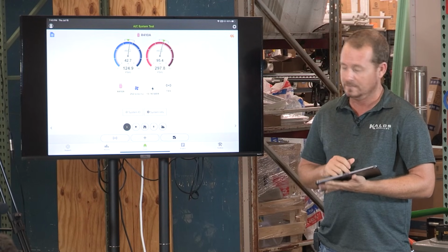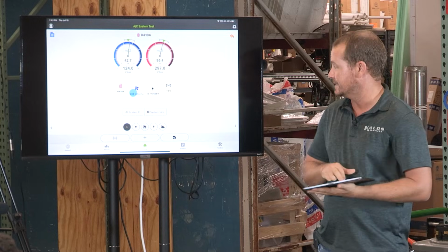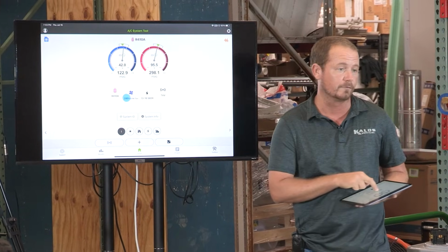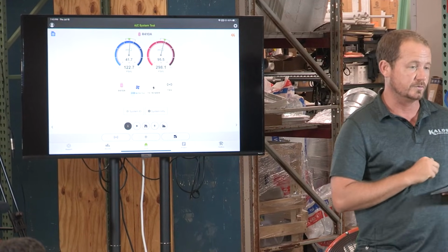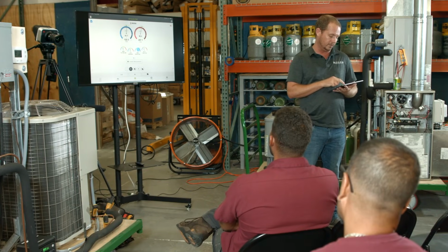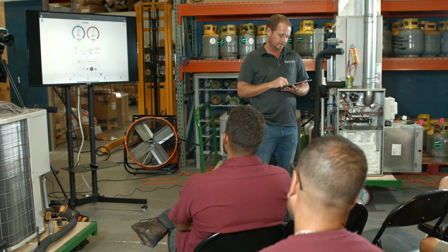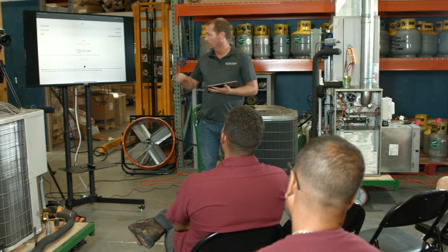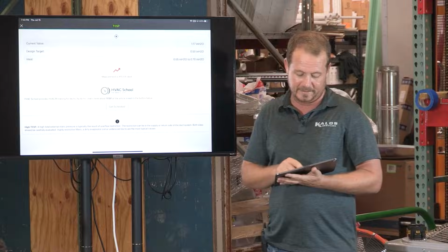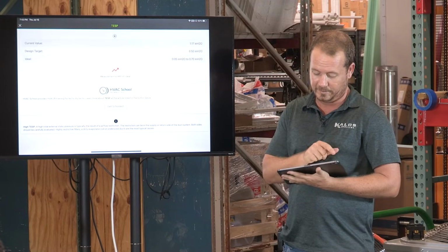Also, Measure Quick knows it's a problem because it's showing we're currently running 249 CFM per ton, which is way lower than we should. And of course, our static pressure is way up here in the red. If you want to learn more about static pressure, you can just go to this website. It's a really good website.